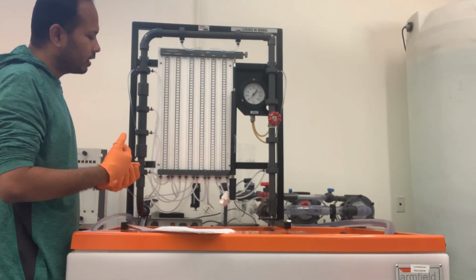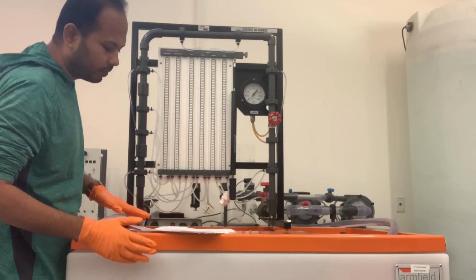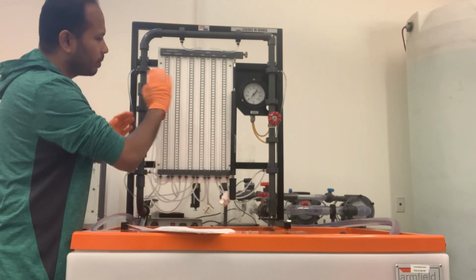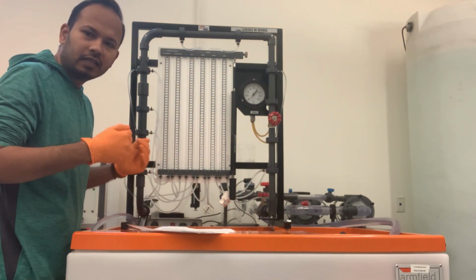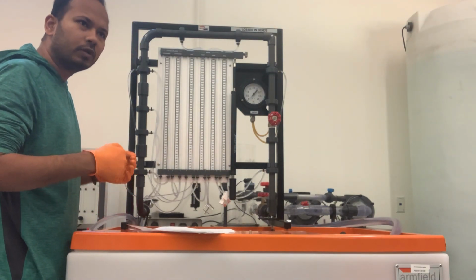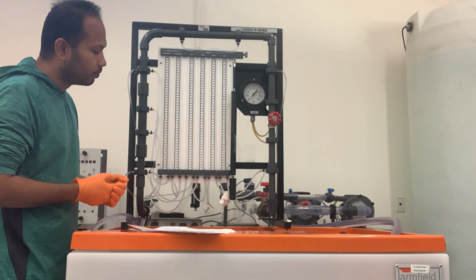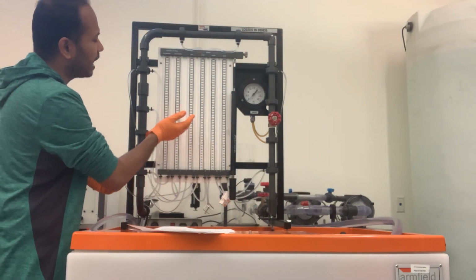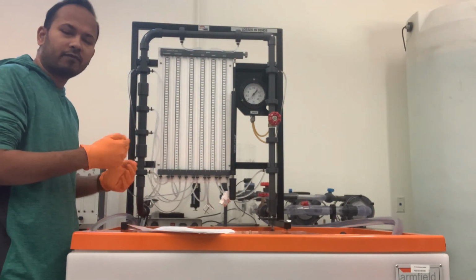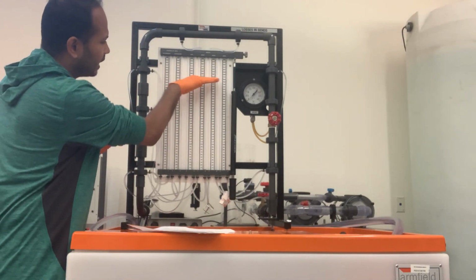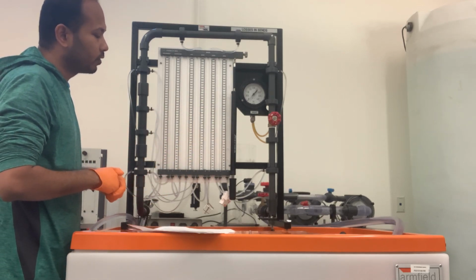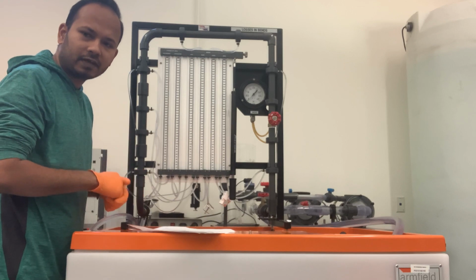Now we have to lower or control the bench valve from the pump so that the water flow rate into the pipe is no more than 17 liters per minute. We have to do that because if we have more water flow, the pressure will be high and we will not be able to take the reading using this manometer. So we have to keep the water flow up to a certain limit so that we can take the reading. Now it is totally full, so we cannot take the reading. So we have to lower the flow rate below or at 17 liters per minute.